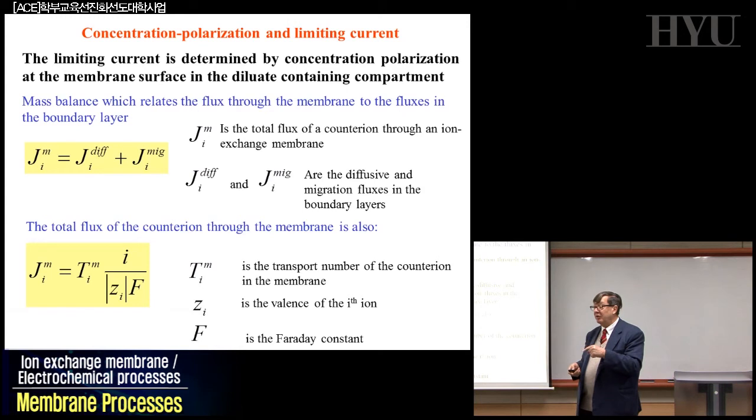and you change pH. You change the concentration of the hydrogen ions, and changing pH can completely change the behavior of your membrane, to the point that it can destroy the membrane. Membrane polymers, particularly polyelectrolytes, are very sensitive to the ionic strength and to the pH of the solution.